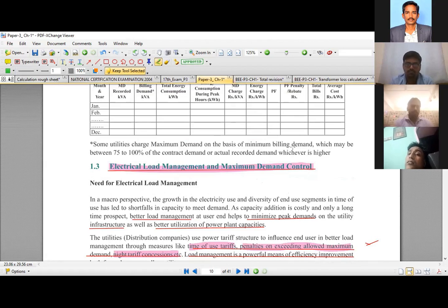Just you can analyze. First you go to the plant, analyze the load curve, then rescheduling, then one job completed. Then what you do? Product storage system, the food industry and refrigeration system, just tell them to use the ice bank, storing at non-peak hour, night time, then use that load in the peak hour. 3 steps completed.